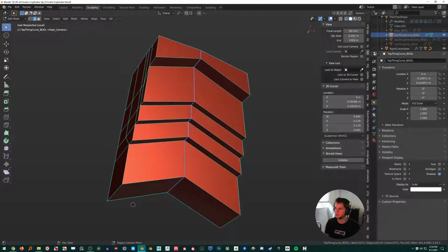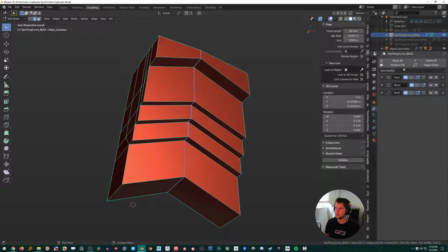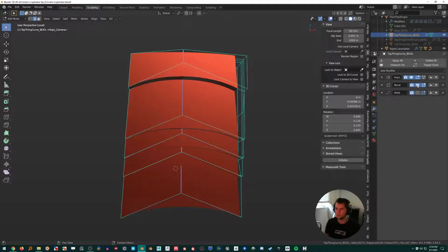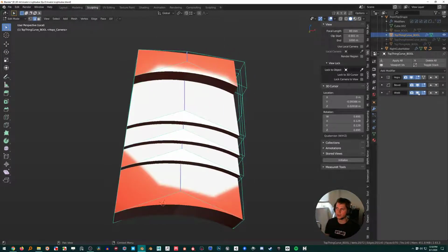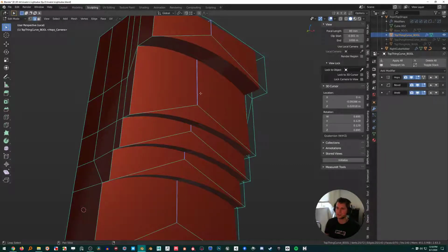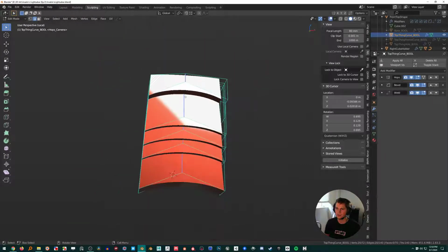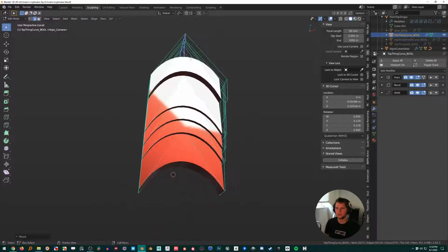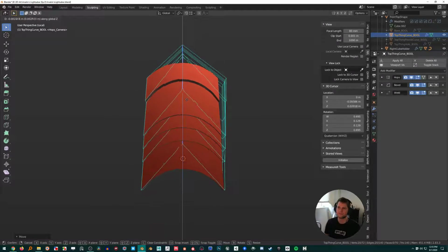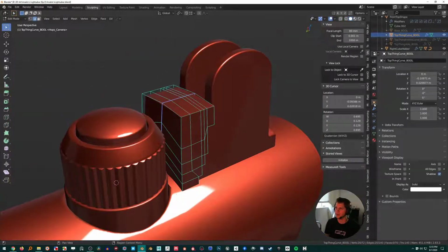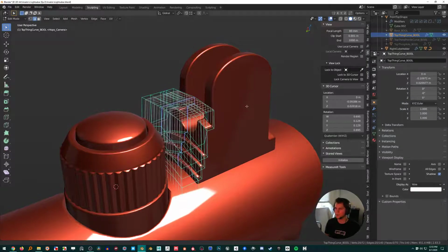And now I've got a mirror modifier on, then a bevel, and then my weld modifier after it. But now I can just select this whole loop and pull this up and get it exactly where I want. So easy. Let's unisolate this and put Y back on.